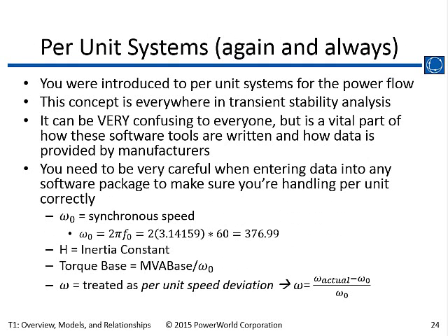One thing that's very important in considering power systems is we use per unit a lot, and most of the data that you get is in per unit. So power engineers are pretty familiar with this. There are tricks in looking at the data. Sometimes it's in per unit and sometimes it's in actual units, particularly when you get into values that respond to frequency.